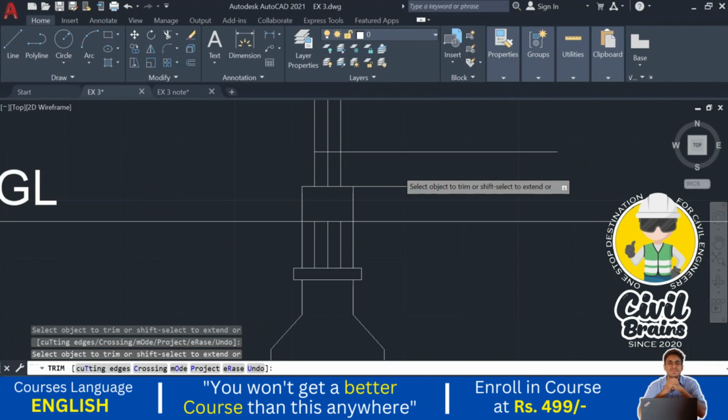Offset 0.225, enter. I just take this one, so that you will not get confused here. So I just draw and quickly trim the things using the line command. I just maintain the slope here to here and here to here, and I just trim.